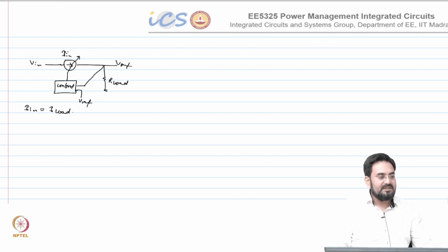In the previous case, you just control it with the resistor divide ratio. So if your input voltage or your output current is changing, you just change the input resistor, so that your output is regulated. Okay, so that is the whole concept behind your regulator, which means you have to build this resistor or this current source. Okay, and how do we do that?